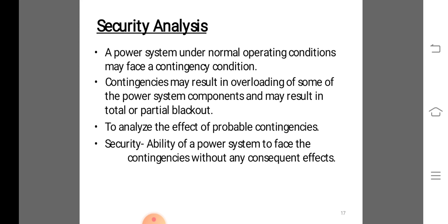Third one is contingency analysis. It assesses the impact of a set of contingencies on the state of the power system and identifies potentially harmful contingencies that cause operating limit violations. Optimal power flow recommends controller actions to optimize a specified objective function, such as system operating cost or losses. It will be subject to a set of power system operating constraints.